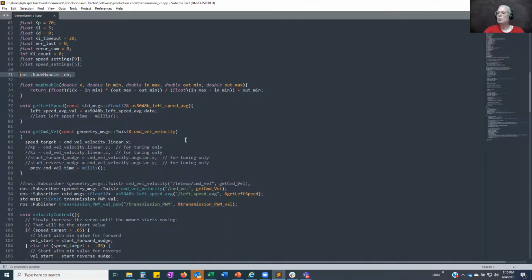Well, regardless of what the messages are going back and forth, the point is you have to have communication between the Teensy and the ROS machine. And now if you have multiple Teensys, the question was how does the ROS machine know that you've got multiple devices, and how does that communicate to that? Every Teensy, you have to start a ROS serial for every Teensy that you start. Okay, that's the answer he was looking for there.